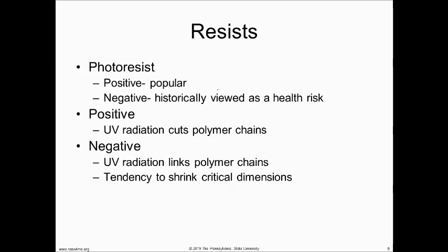When you work with organic polymers, or organic polymer removers, or organic polymer modifiers on our substrate, we have to watch that we're not breathing that stuff in, because we're organic polymers too. So those could be potential health risks. I wanted to make sure that we certainly have time to talk about health and safety in any presentation. So just be cautious around photoresist and make sure you're reading the MSDS or SDS safety sheets on any chemical that you use in nanofabrication. So there's a little safety pop-up window for you, which I think is very important.